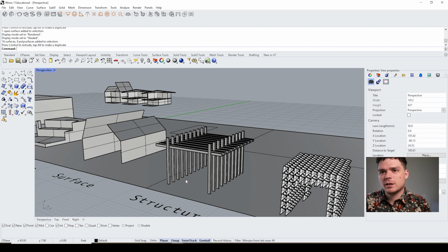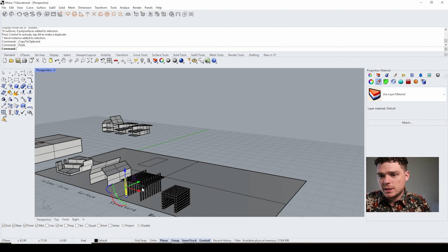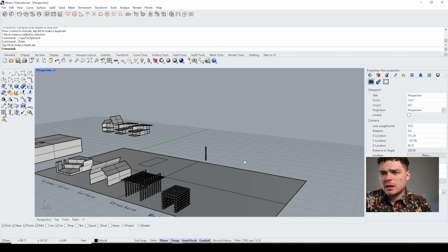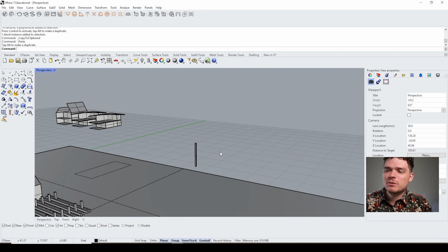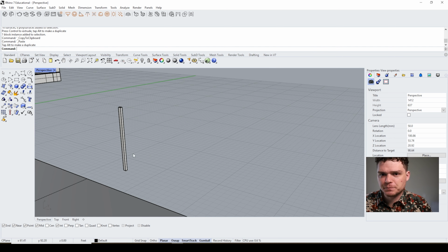So let's go through how we could think through this. Again, it's pieces, it's elements. And again, this might be in a more detailed part. It doesn't have to be, but it tends to be. You're making studs, it's farther down the line of a detailed model, because you're modeling the elements and constructing them and thinking through not just massing an overall concept, but actually thinking of structure, which is the very thing that's going to hold up your project. So it is a little bit more detailed, but it can be a way to generate ideas and design intent.